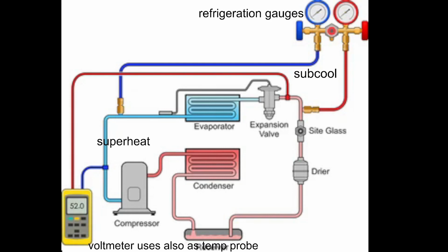It basically knocks off any residual refrigerant in the system and dumps it there, and it can pick it back up. Now, remember I told you about the liquid line dryer. If you look and follow along, you'll see a little gray one. Looks like a little bottle. Looks like it has caps on each end. It says dryer. That is your liquid line dryer. That is your filter.